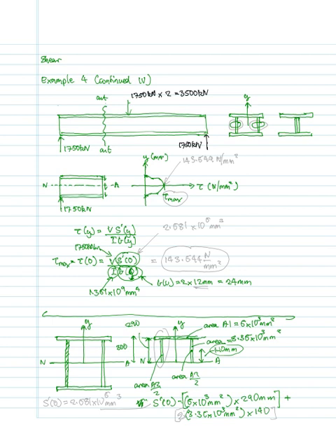So that distance there is going to be 140 millimeters. So 600, being the total depth, minus 40 is going to be 560. 560 divided by 2 is going to be 280, and 280 divided by 2 is going to be 140, so that confirms that.